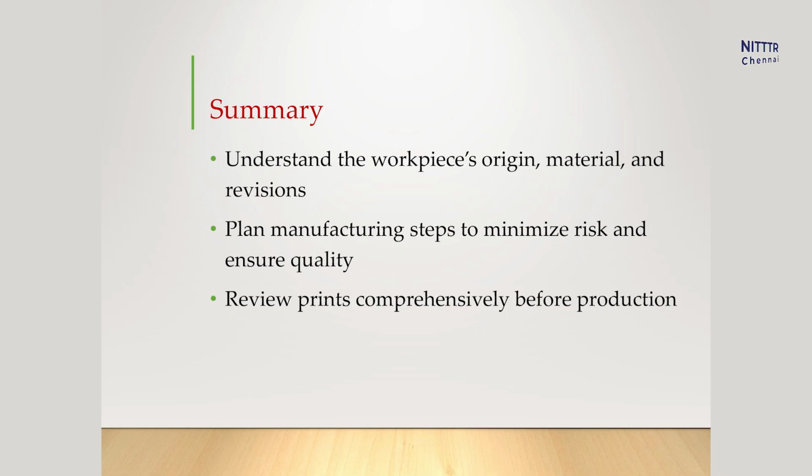Large and heavy components such as engine blocks or aerospace structural elements require special lifting fixtures or automated handling systems to prevent excessive stress and warping. Ultimately, understanding resistance to damage in processing is essential for maintaining product integrity and reducing costly reworks or scrap.